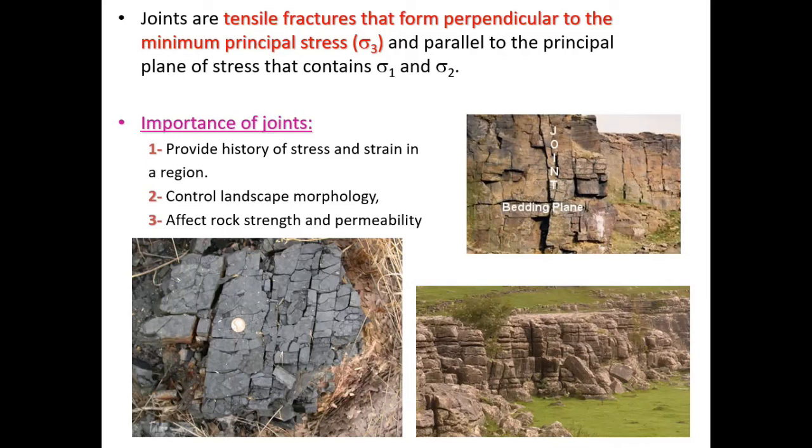So at this time, because we change fluid content and form new fractures, with changing stress and shear stress conditions inside the rock, some previously formed or existing fractures can also slide and produce slip. That's basically a really interesting phenomenon that people still investigate.